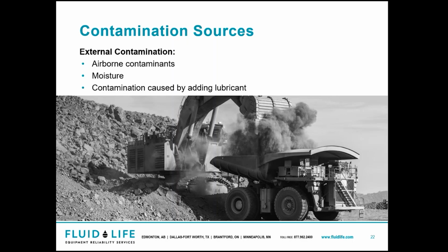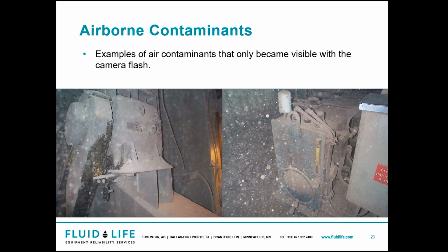Look at something like this stock image of a haul truck getting loaded, right? That dust there, if caps are not in properly, and it even looks like that access panel is open. What if there's something that is allowing the contamination to get in there, right? Making sure things are closed and dampened and everything as it's designed helps prolong and make things last as long as they can.